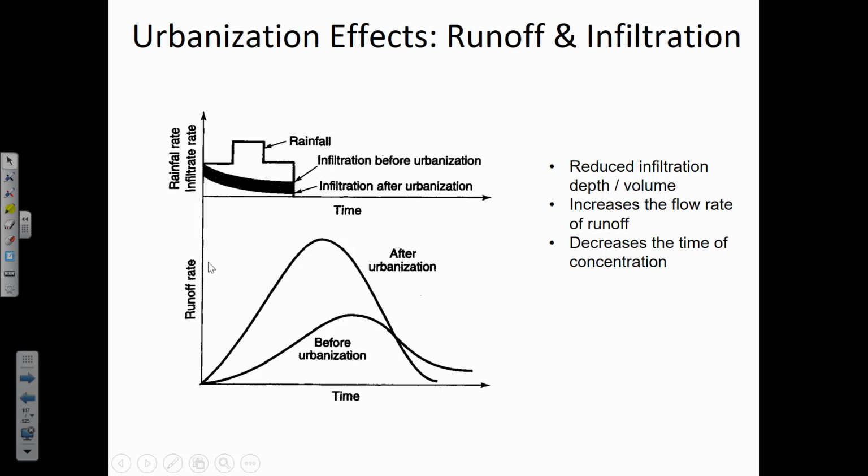And so the way to interpret this figure on the top is that they're measuring rainfall maybe in 15-minute increments. And for the first period, the rainfall intensity was some amount, and then the second 15-minute period, the rainfall intensity was higher, then it stepped down again. So what we're looking at on this top figure, the hyetograph, is 3 different periods when there was a certain amount of rainfall intensity.